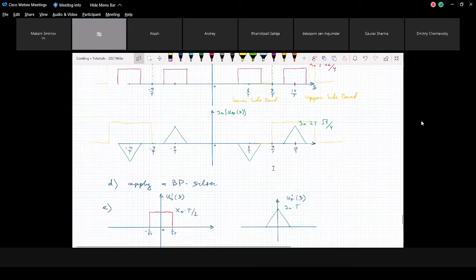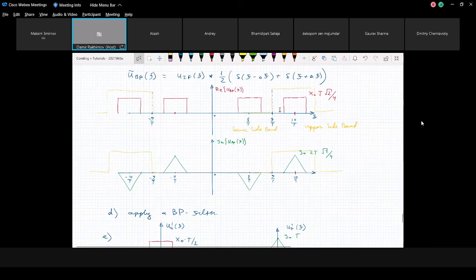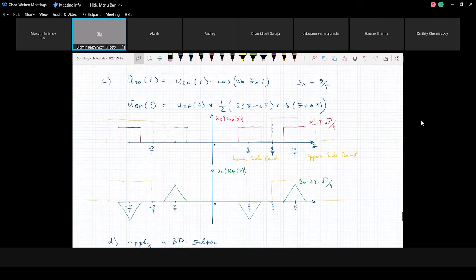When you have such a signal, when you multiply, remember that when you multiply by cosine, you shift something to the right and something to the left. One copy you shift to 0, and another copy you shift to the frequency 18 over t, I think, if we perform with respect to 9 over t. So you will have some components at very high frequencies, and you need to remove them. You remove them by applying this low-pass filtering. For this reason, we have this second low-pass filter.